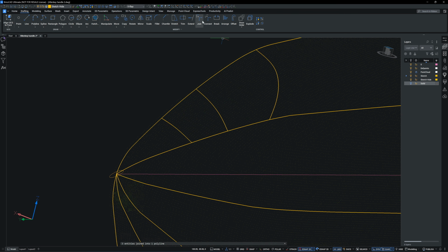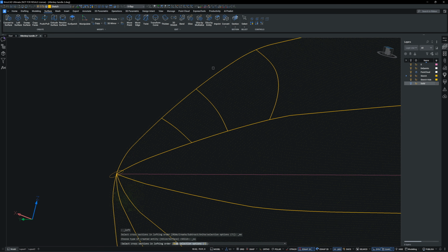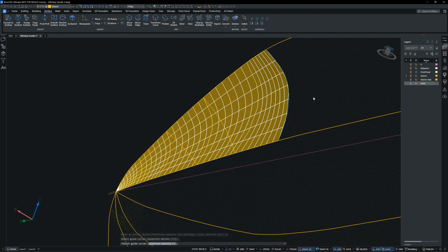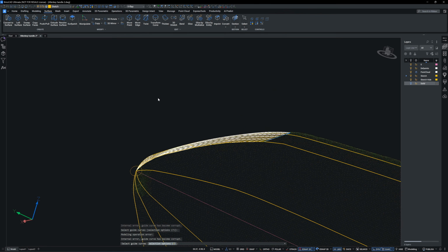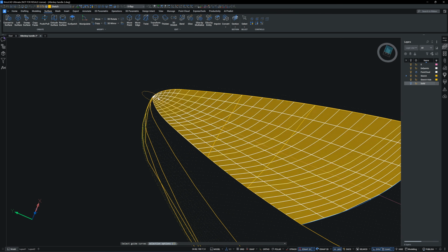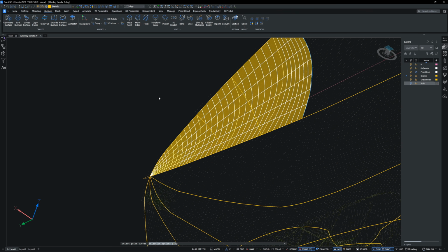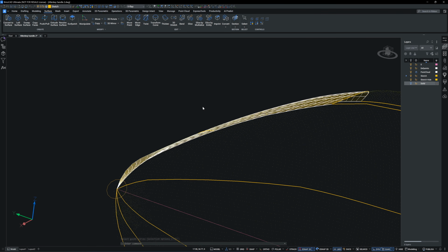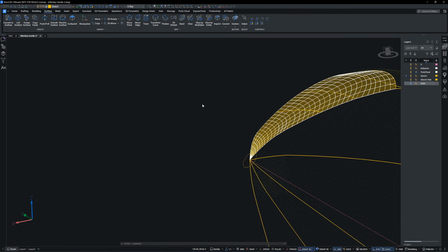By contrast, the surface loft command performs very well, so I will use loft as the main modeling tool. All you need to do is select two loft sketch profiles and close them with guide rails. You can also add additional guide rails in between to force the surface to fit the point cloud.